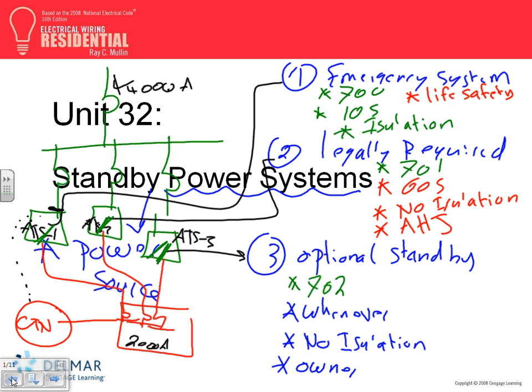Number two is, accidentally somebody closed the circuit breaker. Now guess what? Not only are you feeding your panels and your load in the house, you're actually transforming the 240 power, or 120 in this case, 120 power all the way to 13,800 volts on the transmission line. Because the power goes up through the transformer, all the way to the transmission line. And if the transmission line people are working on the transmission line to fix it, you burn somebody. So that's why they don't want you to plug it into an outlet. A lot of people do that though, in residential. They plug it into an outlet, energize the house.